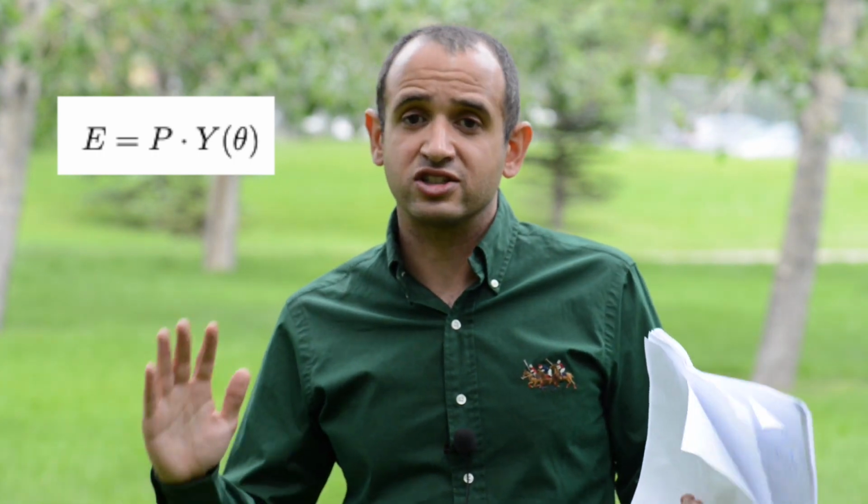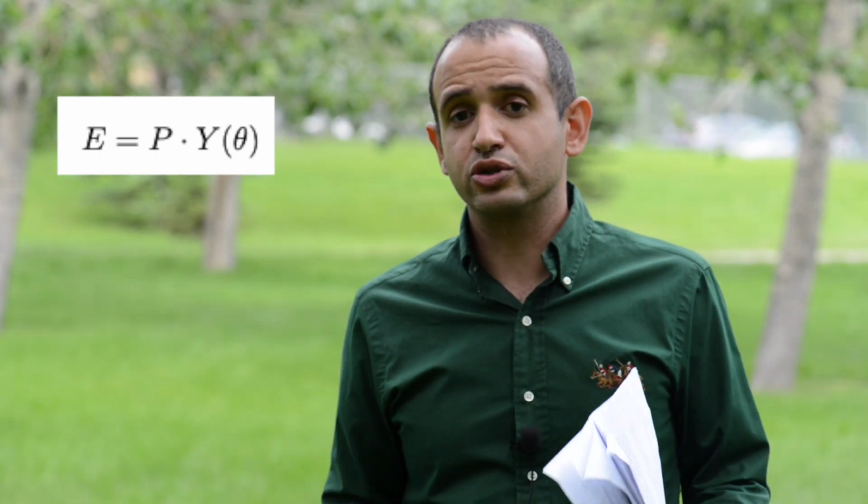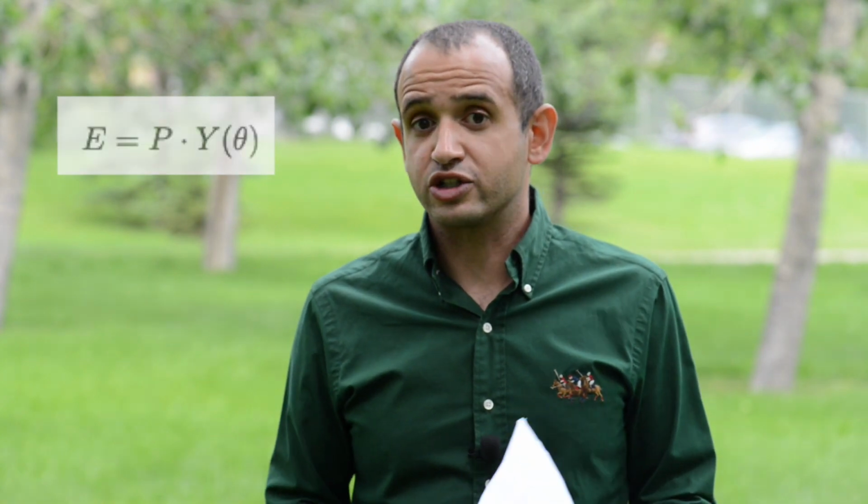If it's a 2 gigawatt system with a yield of 900, it will produce 1800 gigawatt hours per year, and so forth. For this paper, to derive that relationship between tilt and yield, I used data from NAIT's solar array in Edmonton, Alberta, Canada. At NAIT, we have a multi-tilt solar array, 14, 27, 45, and 53 degrees, I believe. Using that data, I did a first order regression and some statistical analysis, and the results are in the paper as well. We're going to run through them.